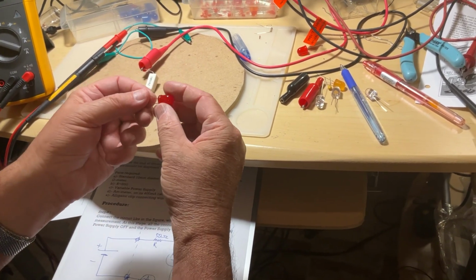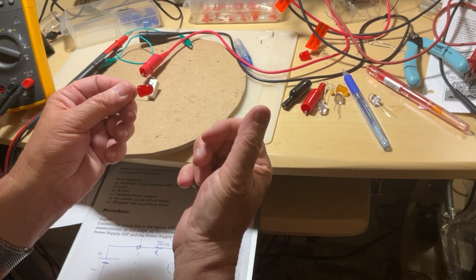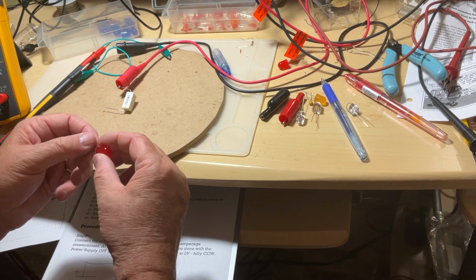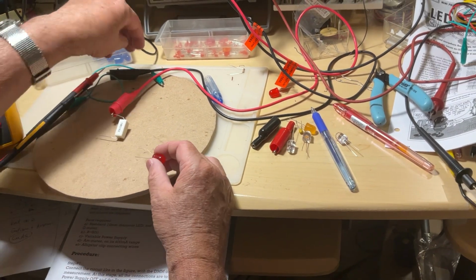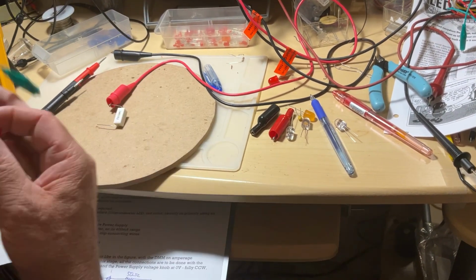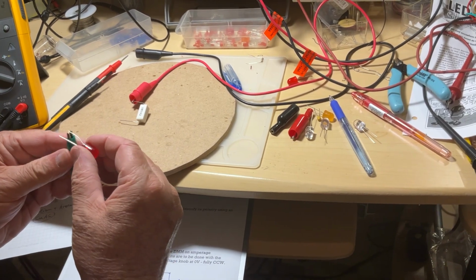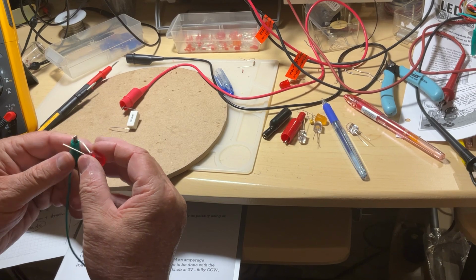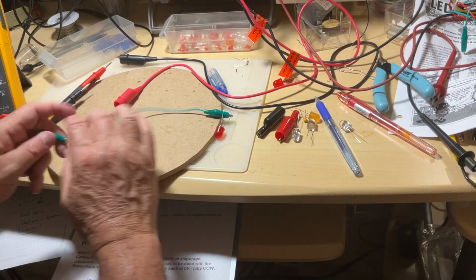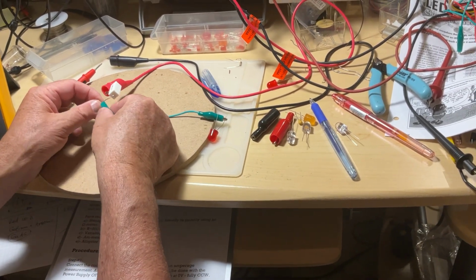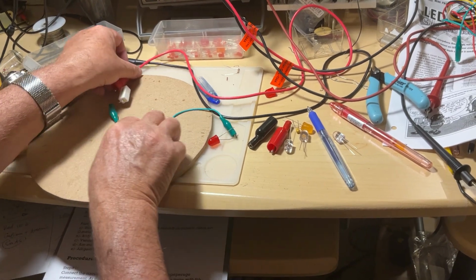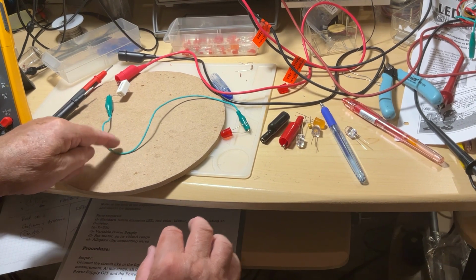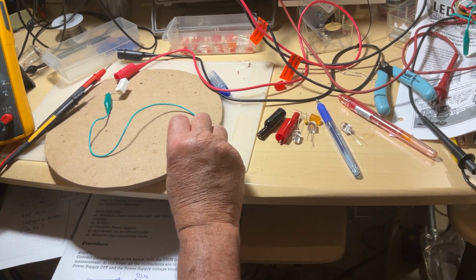We're going to talk about that next time when we build the testing circuits. How do you identify the anode and the cathode properly on a diode, on an LED? Now we just make the connections. If you don't know how to identify, you're going to measure with the multimeter first. So we connect the diode to the resistor. You keep a distance from the resistor to any other component, including the insulation of the wire, because it may heat up.